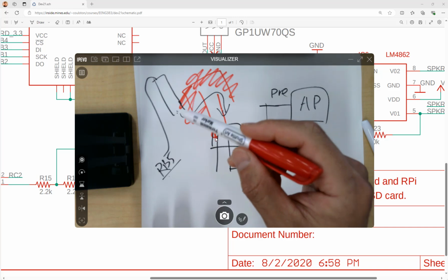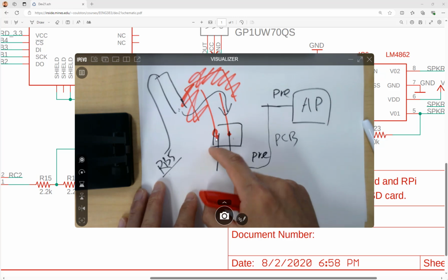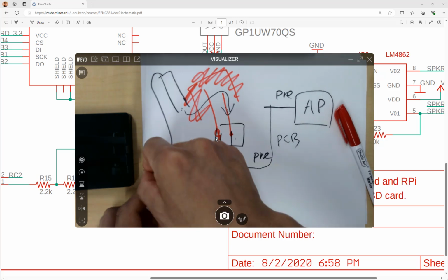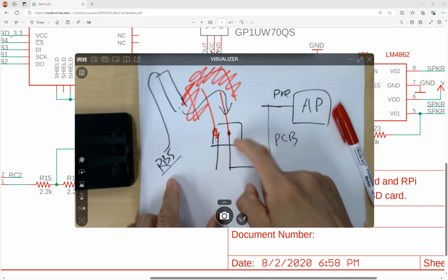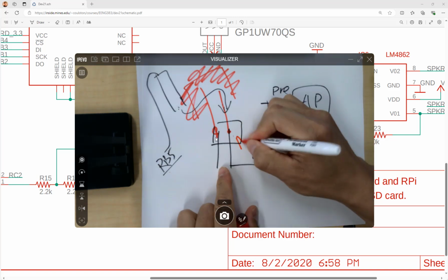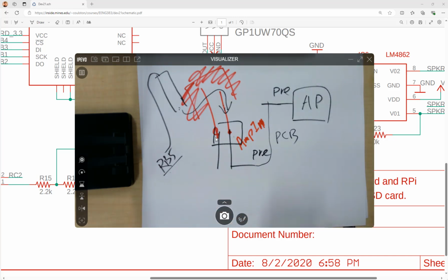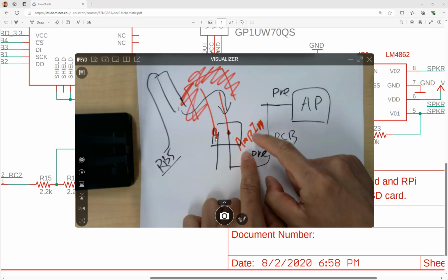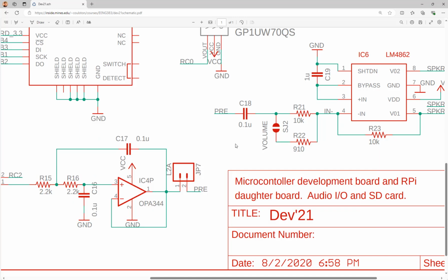Does that make sense? So in lab 3, actually, that's what we did, but probably you didn't know why. So now here's why. You got the RB5, there are male header pins of the microcontroller, right? You use the two female cables, connect, and the other side of the cable, you plug into, I think it's amp in on the board. You can look at the silk screen, the print. So the amp in, the amplifier input. So the low pass filter is not engaged. Does that make sense? Okay, so you know what you did. And now let's come back here.